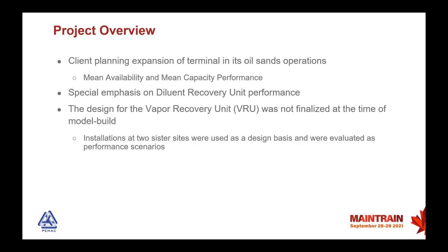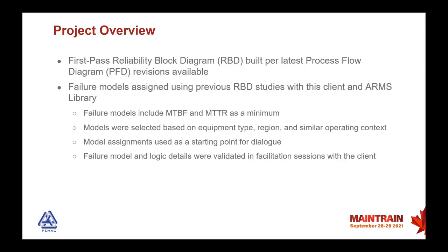One interesting point was that the design choices were not finalized yet for their vapor recovery unit. And so what I did was simulate multiple scenarios, using existing VRU packages as a basis. The package performance details came from sister sites' vapor recovery units. So the first pass diagram was built per the most recent process flow diagrams that were available.